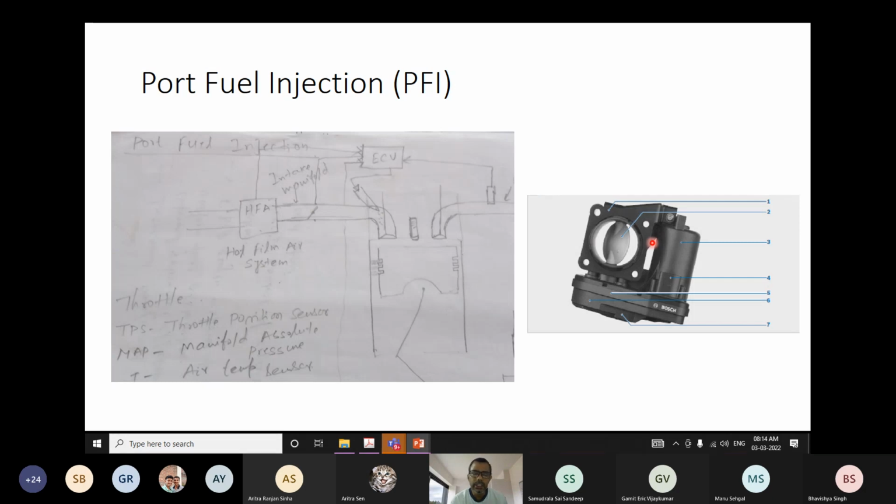But now the control system is based on torque demand based calibration. What is the torque demand? Torque based demand signals mean, let us suppose, that when you are starting the engine, your music system or even the AC might be on. When you are turning the key or running the engine, the engine needs a lot of power, but at that time you are not pressing the accelerator. Then the torque demand is more, because it is not only starting, but other auxiliary systems also require some power, and that power has to come from the engine.